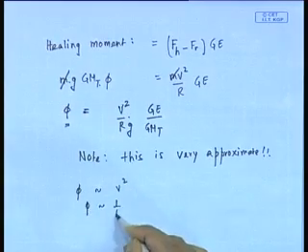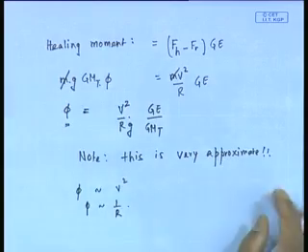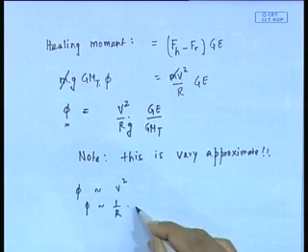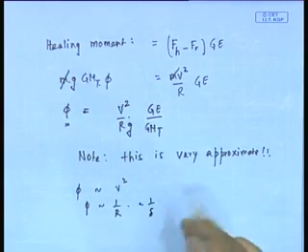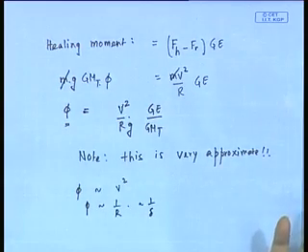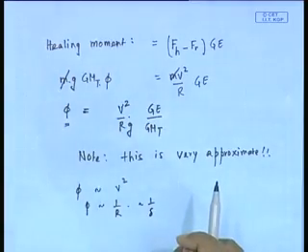It means if you go at higher speed, yes, you may have a larger turning radius, but you are going to heel more. Phi is inversely proportional to R, that is proportional to 1 by R. You have a tighter turn, you heel more. So if you get a larger rudder, obviously larger rudder angle means tighter R, means 1 by R is proportional to delta, isn't it?